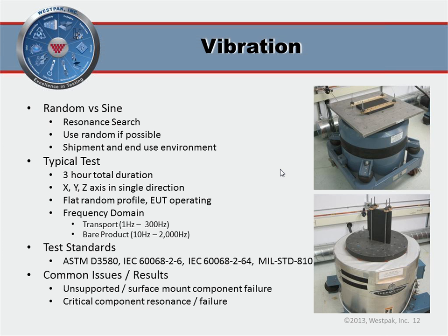Common issues we see with a product like a laptop, or maybe something a little bit bigger, is hardware backing out if you don't use any sort of locking hardware or thread locking stuff. Commonly, we'll have a big box, we'll do 3 hours of vibration, we open the box, usually you can hear it while it's going, and there's a big pile of nuts and bolts on the bottom of the casing. Oftentimes, either, again, people didn't use the right hardware, or they didn't specify torque.